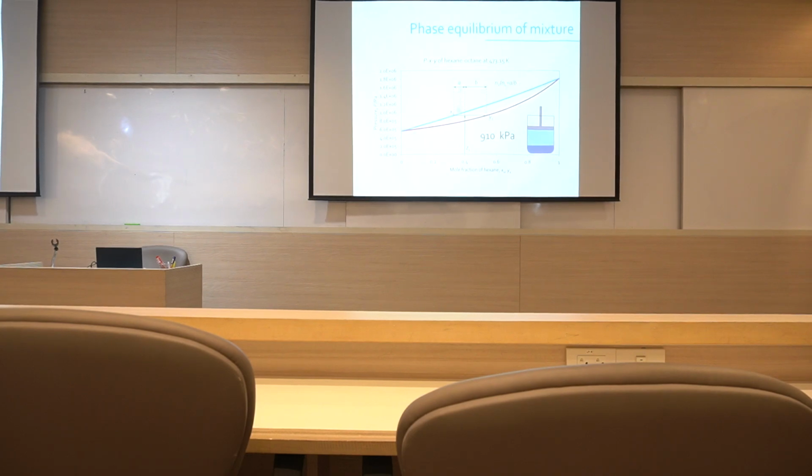A is the difference between x and z, so basically just z minus x, that is your A. Over B, where B is y minus z. That equation is called the lever rule, L-E-V-E-R, lever rule. Basically, it's for material balance. So if you wonder where this comes from, you can try doing some material balance, and it will end up at this equation here. So from the phase diagram, you can also find the ratio of the two phases, NV over NL.